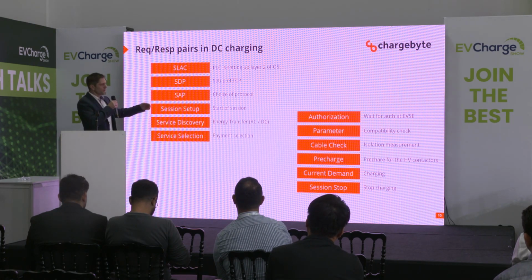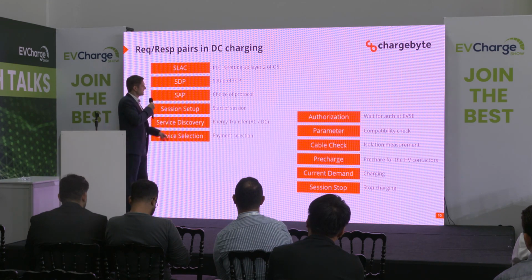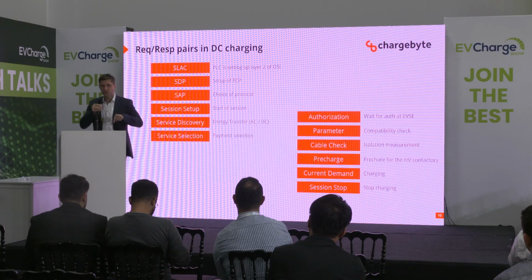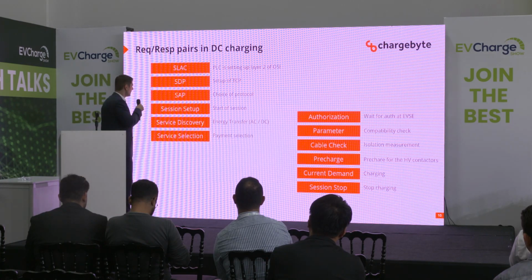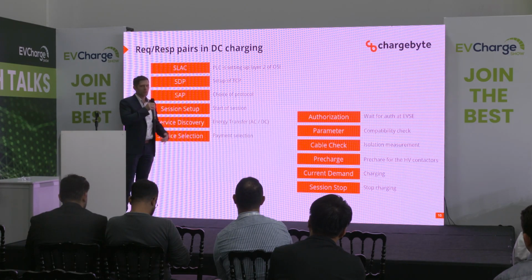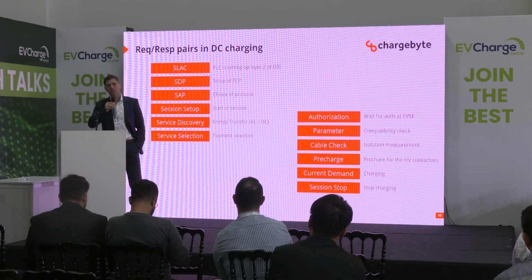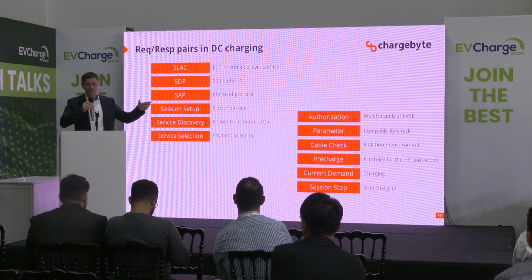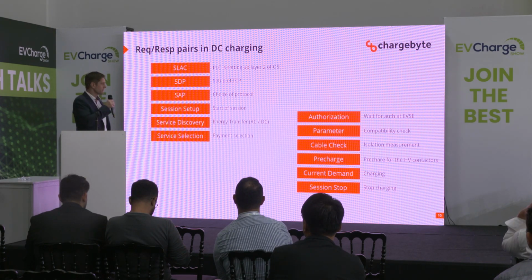And then the protocols are relatively similar. Then we start a session, handing over a session ID so that you know which session you are on. On that session, we then check which energy transfer we do and which payment information. Is it AC? Is it DC? Is it payment via plug and charge? Is it payment via an external identification and authentication?